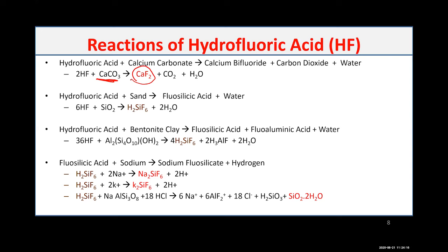If you have a formation, even a sandstone formation, that has a high calcium carbonate content, usually people say like above 20%, we never bump HF, because you will have a calcium fluoride precipitation and significantly reduce the porosity and permeability. And instead of having enhancement, you're most likely increasing your damage. So you do not bump HF in a formation that has a high calcium carbonate content, or definitely a carbonate formation. However, if you are bumping with a formation that's pure silica or really high content of sand and clay,